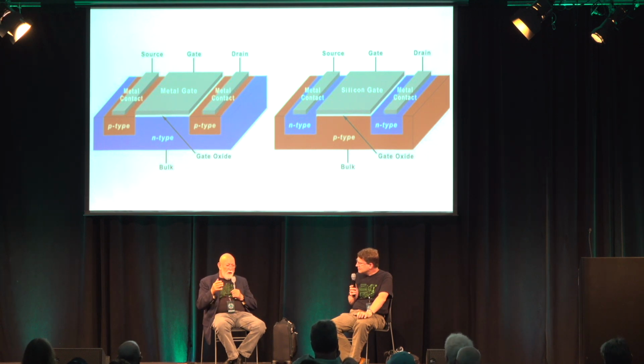He was part of the team that came from Motorola, and so he worked with the process. And see, because my process monitor that I created at Motorola, I split it down the middle. I had everything aligned with the crystalline structure of the silicon wafers. So I had them all lined up the same way so that I could test the enhancement mode process and the depletion mode process. So I actually knew what we could do at MOS Technology.